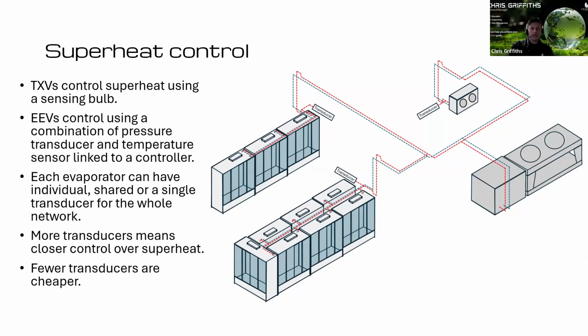They're best shared across it, I would say. So if we took that island of 7 cabinets, for example, 2 of them were iced up, 5 of them are operating okay. The first point I would look at is it's probably not transducer related. It'd be more of a controller issue, say a superheat issue of miscalculating the valve opening positions based on those transducers. Because if 5 are working okay and yet 2 aren't, you can almost rule out the hardware issue there, because otherwise all 7 would be faulty.